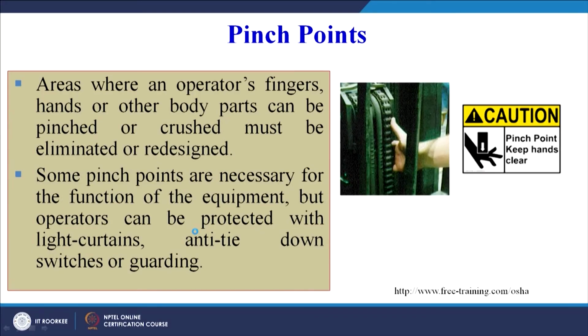So pinch points are very common in industrial scenarios. We must avoid the pinch points through guarding or through whatever mechanisms or equipment that we can use. Areas where an operator's fingers, hands or other body parts can be pinched or crushed must be eliminated or redesigned. Some pinch points are necessary for the function of the equipment, but operators can be protected with light curtains, anti-tie down switches or guarding. So we must design the equipment in such a way that these pinch points are taken care of.